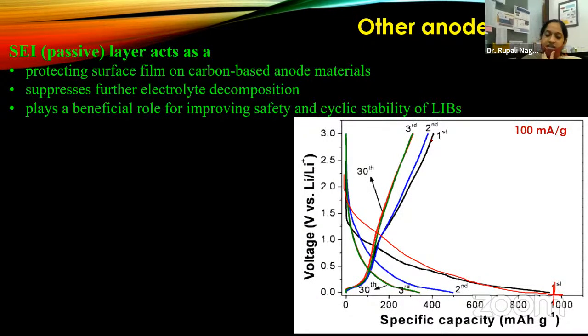And then as the cell is used, we have already talked about how the potential drops across the ohmic region, the activation region, and the mass transport region. So this initial drop which you are seeing over here is nothing but your formation of SEI phase. This passive layer is actually forming and eating up some of the voltage from your battery.